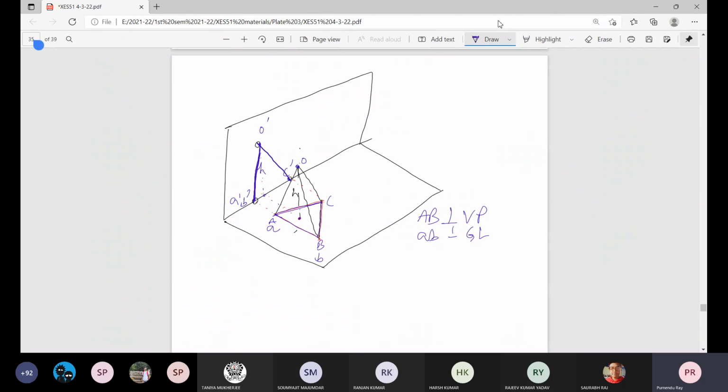And in plan, we identify the location O, connect it with A, connect it with B, connect it with C. That will be the plan of OA, plan of OB, plan of OC. Now, as you know, 6 lines are there: AB, BC, CA, the base triangle lines, and OA, OB, OC, those side connecting lines. So naturally 6 lines you will get in plan and elevation. In plan, this is AB, this is BC, this is CA.